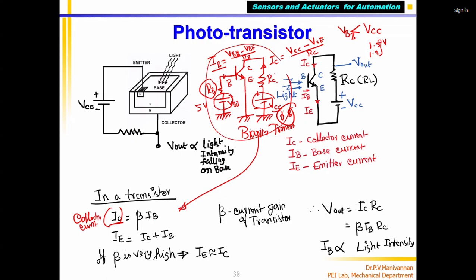If you buy a transistor, you need to see 5 important parameters. Note down. First one is what you call VCC, that is called collector supply voltage. For a given transistor, the manufacturer will say how much you can give, say 3 volts. Minimum is 0 volts, maximum I call VCC max. Maximum 3 volts. Some transistors say 5 volts. Somebody says 10. Somebody says 100 volts.